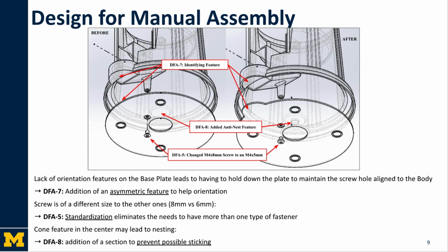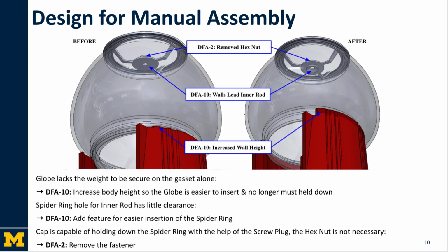Finally, the central cone of the baseplate could cause parts to stick when stacked. We added an anti-nest feature according to DfA 8 to prevent sticking and make part retrieval faster and more reliable. For the globe and spider retaining ring stacking, minimal changes with big impact were implemented.